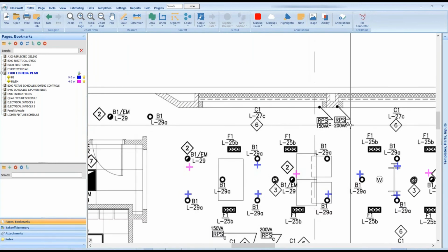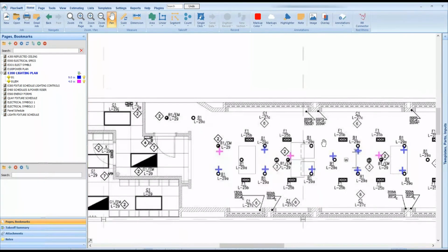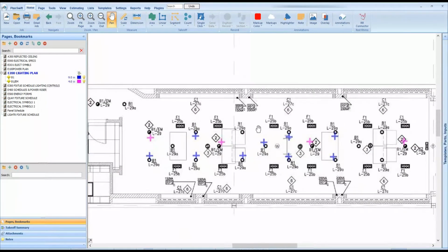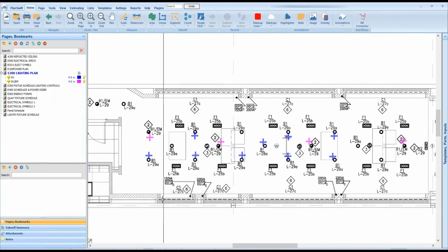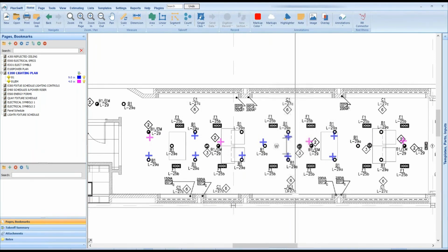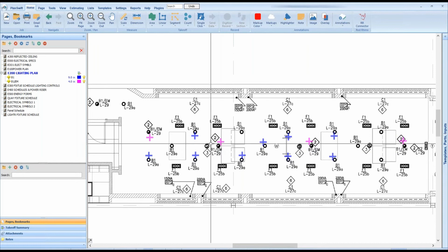Now let me back out of this so we can get the big picture here a little bit. In a quick reference, these tape lights are the same length, probably these 3, 4 and 5 of them, with 2 other ones down here. So all I need to measure is 1 of these, and I just know that there's 5 the same size, and then I'll go measure these. These are actually the same size also. I'll measure 1 of these to come up with the quantities I need. And again, I would just write this on the takeoff sheet, or I should say on the light fixture schedule.